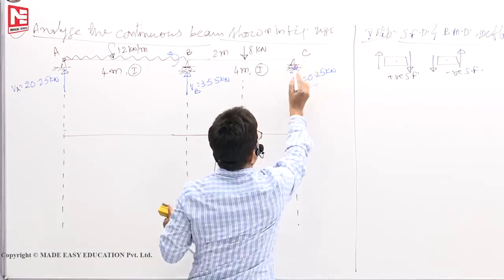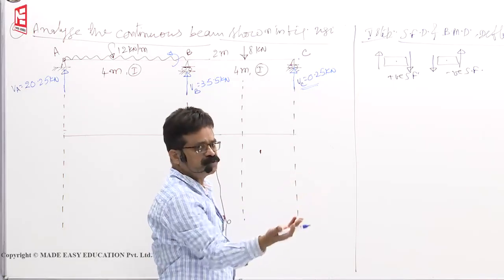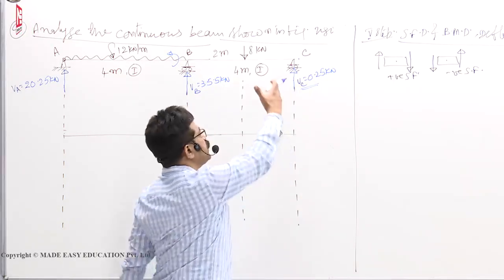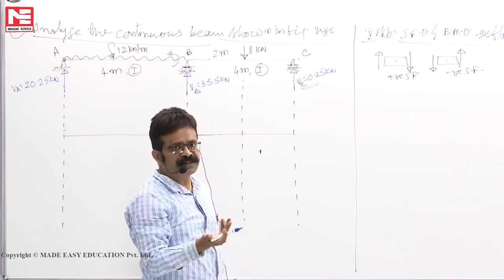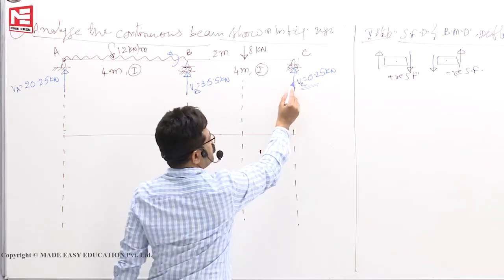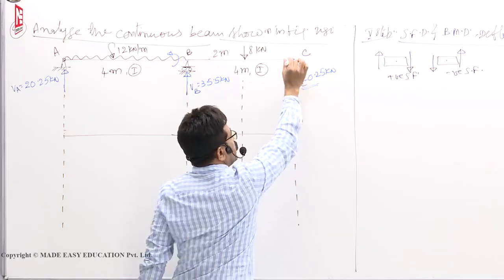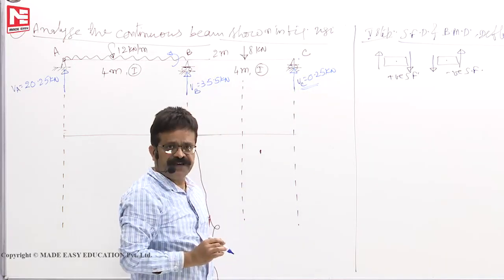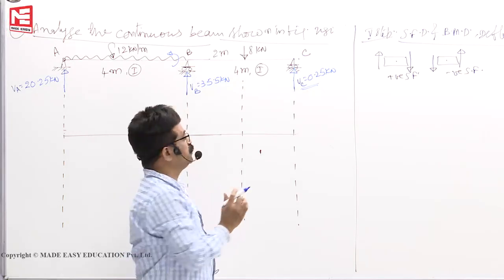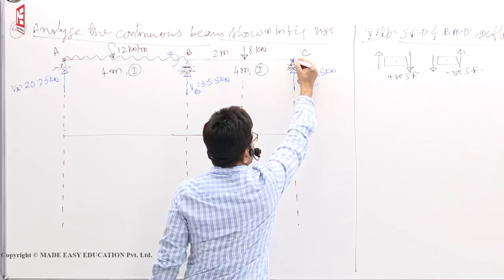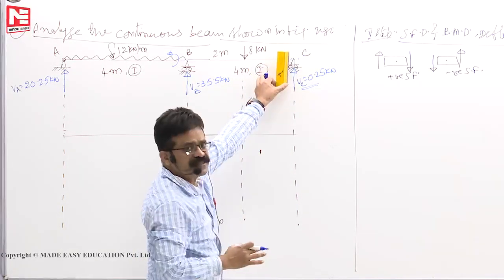Shear force at RHS of C means here. At RHS of C there is no shear force, because there is no beam at all. So it cannot shear anyone. So we don't calculate. At C shear force is not defined. Means shear force is indeterminate exactly under a point load. So you have to stand at LHS of C.